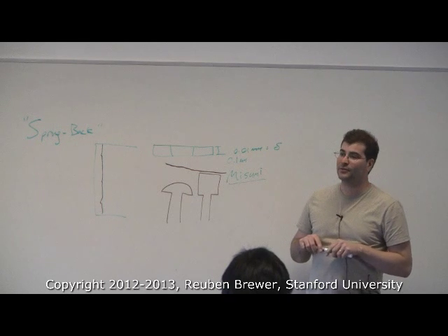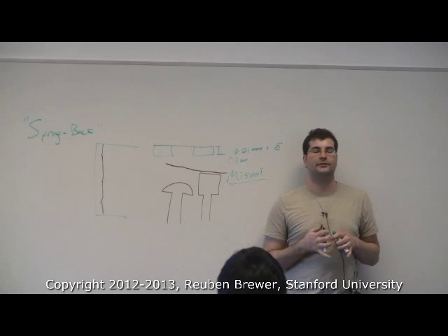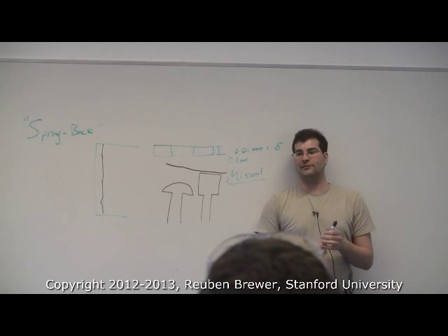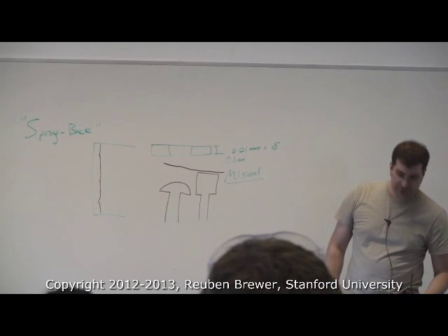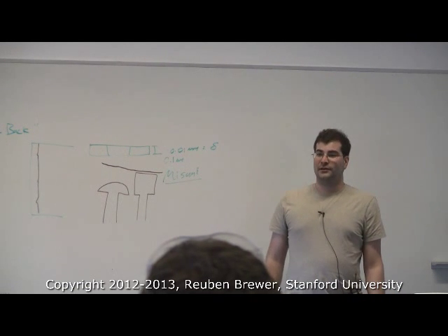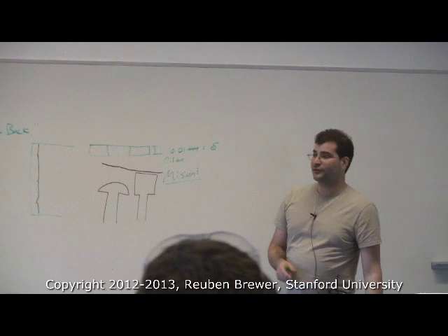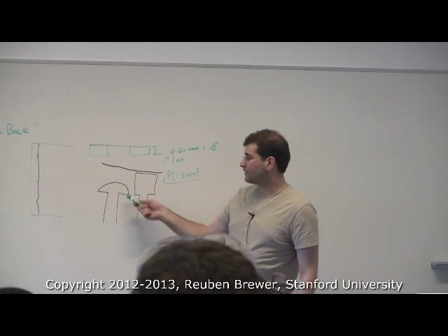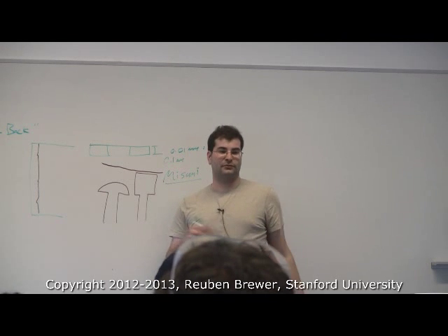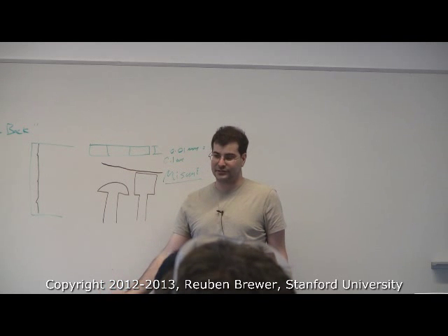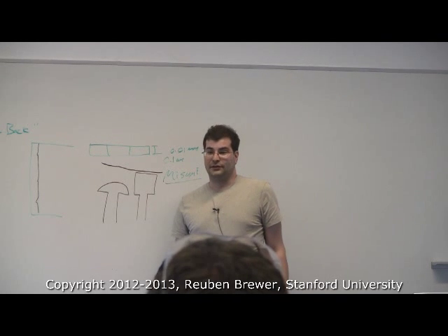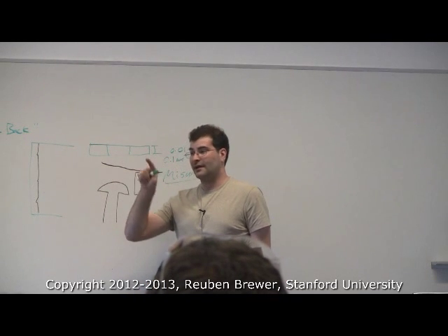Okay, another thing is calipers. Yesterday we had, I don't know, 8 or 10 people in the back room and not a single set of calipers. Now, I'm not blaming all of you. I haven't thoroughly indoctrinated you yet. You should never be assembling anything without a nice set of calipers sitting right next to you. Because if you're using shims and you're not measuring to verify their thickness, you're going to have some error like this. I always want to see people assembling with calipers and measuring things as they put it in the robot, because in my dissertation robot I've got literally thousands of parts. They all look identical to me at this point, and the only way I differentiate them is by checking against the CAD and then measuring with calipers.